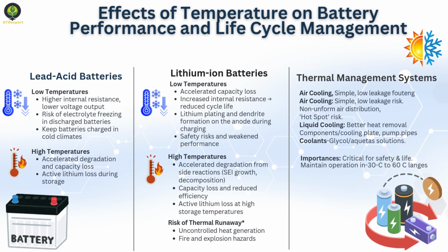Temperature significantly impacts both lead-acid and lithium-ion batteries. In cold conditions, batteries experience increased internal resistance, which directly affects their power delivery. For lead-acid batteries, this also brings the risk of electrolyte freezing, especially if the battery is not fully charged. On the other hand, high temperatures accelerate chemical reactions, leading to faster degradation and increased self-discharge in lead-acid batteries.